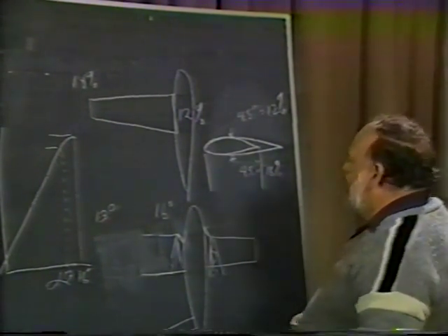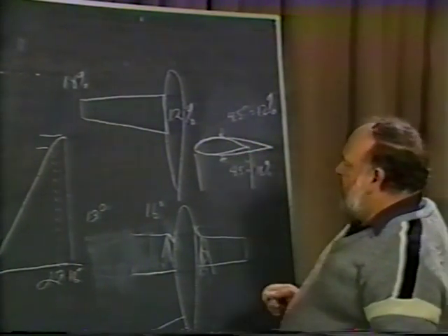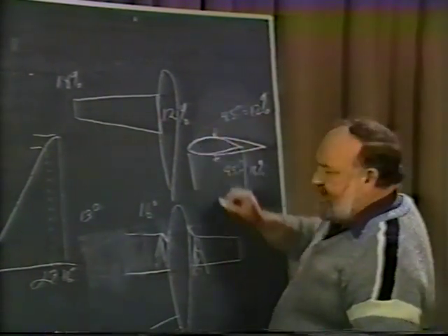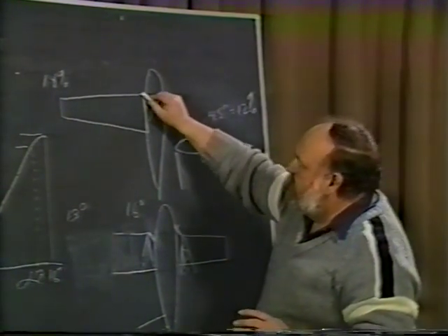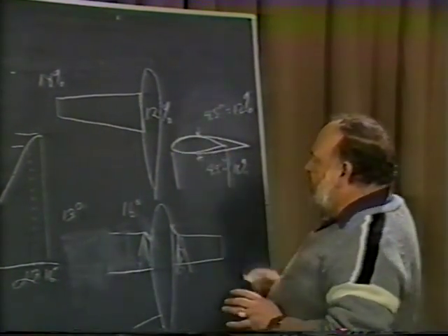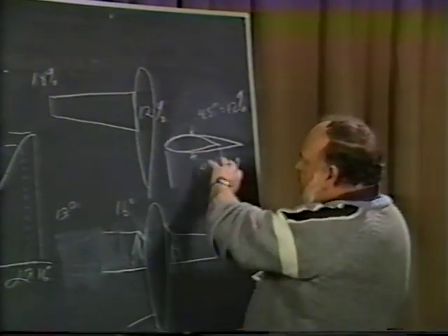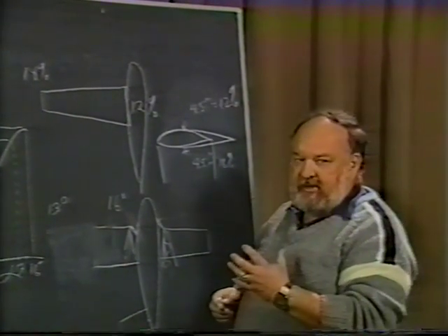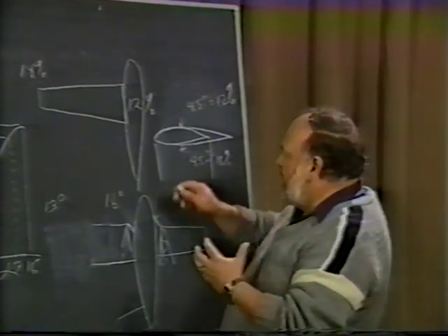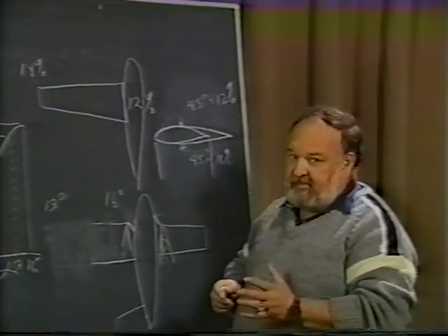Now what does this mean? Well, it meant that we ended up with an airfoil section outboard that had a leading edge radius in actual physical inches the same as it is at the root, but percentage-wise much, much bigger for the tip airfoil section. And therefore, when you have a thick airfoil section with a larger leading edge radius, it will give you a much higher angle of attack before reaching stall, and sometimes a much higher CL.